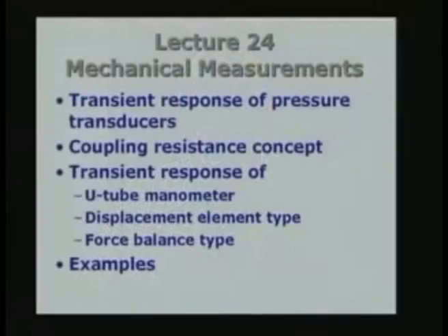So, this will be lecture number 24, mechanical measurements. We have been looking at measurement of pressure and various aspects have been covered already. In the present lecture we look at the transient response of pressure measuring devices. What we will do in this lecture is to look at how the pressure transducers respond to pressures which are varying with respect to time.